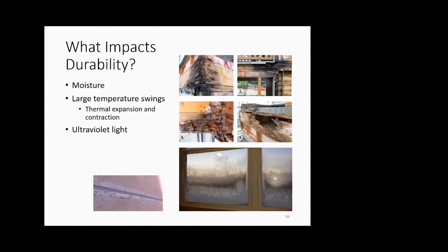But if you don't have a vapor barrier, or if you have something leaking on top of your vapor barrier and you just have puddles down there, if they didn't do a good job putting that in, or it's sealed too tightly and there's no dehumidification, you'll get mold growing, and it's not good for you, and it's not good for structural durability. Mold can deteriorate wood and cause it to rot. It will affect the lifespan of lots of materials and finishes.